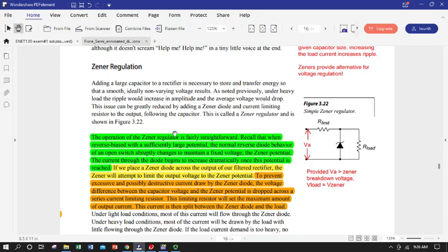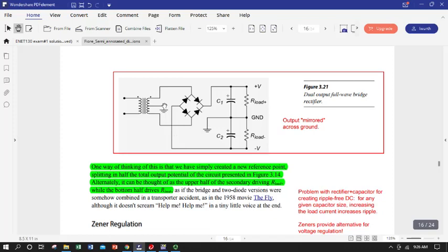So if you were using a capacitor, for instance, in your output circuit here to smooth between the points and continue your voltage signal at a closer to true time invariant DC, by putting those peaks closer together with full wave rectification, you made your job easier.